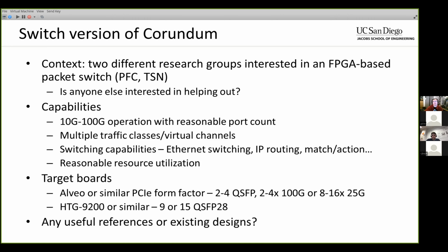Yeah. Well, I guess part of it is you can make it modular, and then you can substitute in the appropriate implementation of a particular module. So, for example, if we have an ingress module, which is performing the routing decision or whatever, then you could have a couple different versions of that. The nice thing about being on an FPGA is you can swap stuff like that out without too much difficulty, right? You can't do that on an ASIC. Well, not without too much difficulty, because rebuilding the design might not be easy with timing closure concerns and placement constraints and whatnot. But at least you can reload it, versus an ASIC. You got what you got. Yeah, no way.